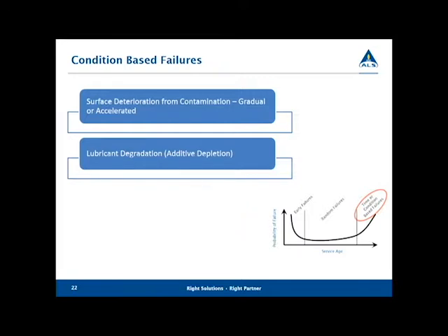When you do oil analysis, you see your various organometallic componentry in a brand new sample, and those levels really don't change over time unless it gets diluted out or sweetened with the wrong oil, but their functionality changes. If you have zinc dithiophosphate in your oil, you're always going to show up with zinc and phosphorus, but the functionality of that changes over time. The same thing with maybe calcium in an engine oil. It's always going to be in there unless it's diluted out, but the functionality changes.